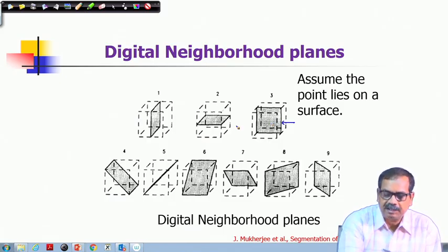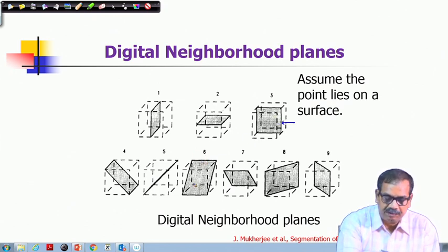There are certain indexes by which these planes are referred to here. For example, the index here is 3. So, there are 9 such configurations, and all of them are formed, as you can see, if I consider this cubic face, either by the principal planes parallel to the faces of the cube, or the diagonal planes which connect the corresponding diagonal edges and show this plane.